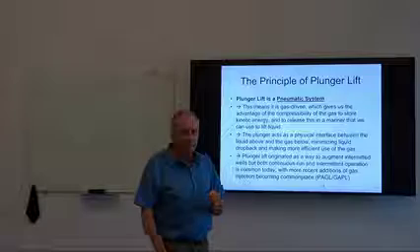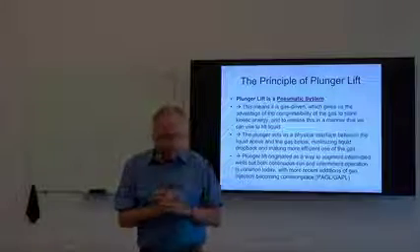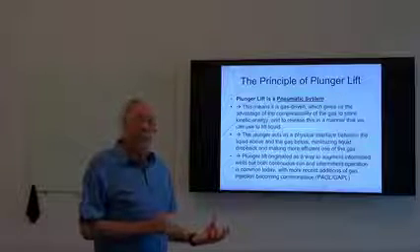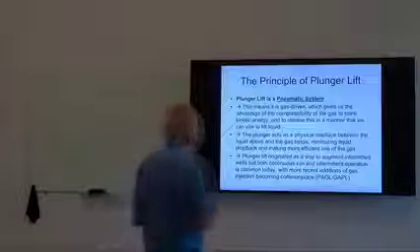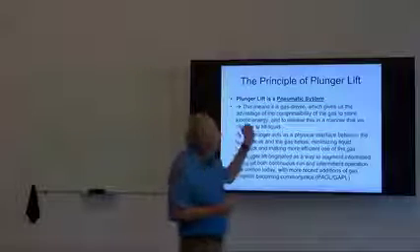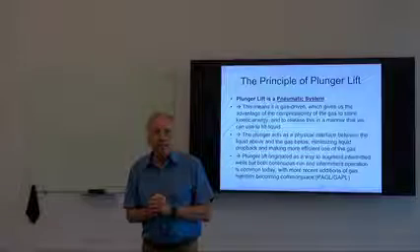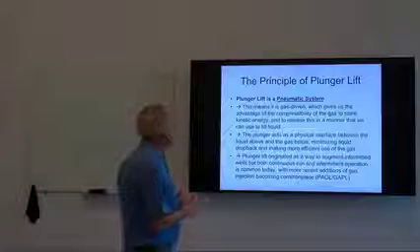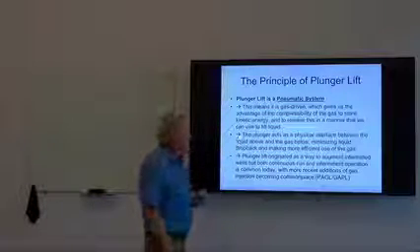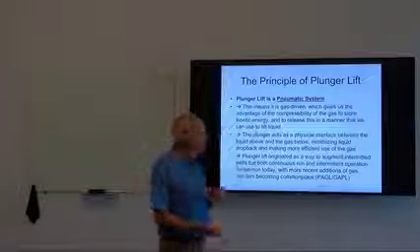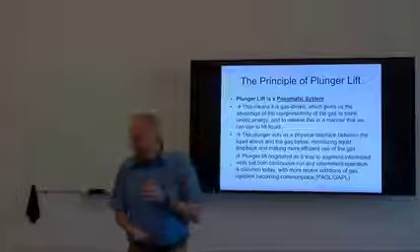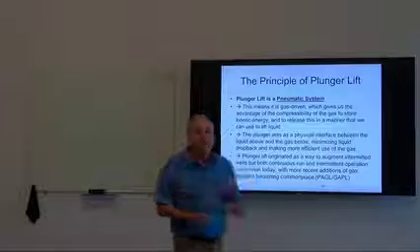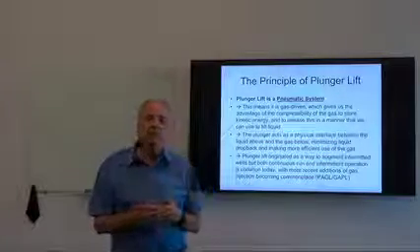It gives us an advantage in several ways. One of which is we have this power of the pressure in the reservoir, in the formation, and the compressibility of that gas to store kinetic energy. And we can release it in a manner that we can use to lift liquid or a plunger. The plunger acts as a physical interface between the liquid above and the gas below, and that minimizes drop back and makes more efficient use of the gas and of the energy that is in the reservoir.